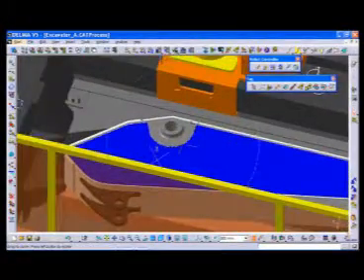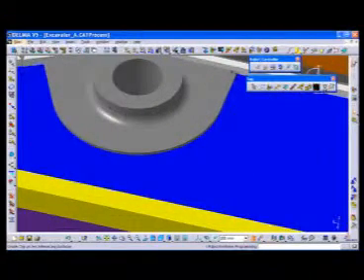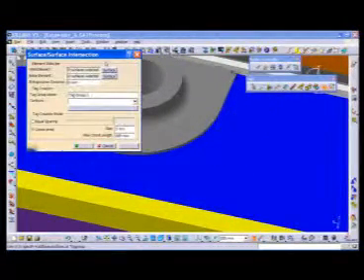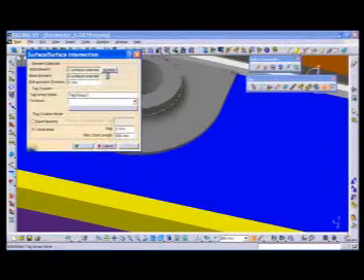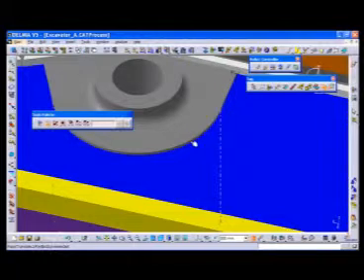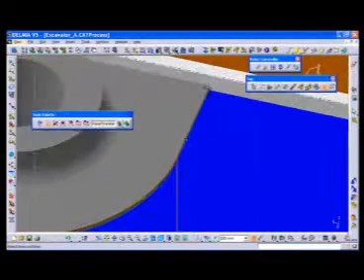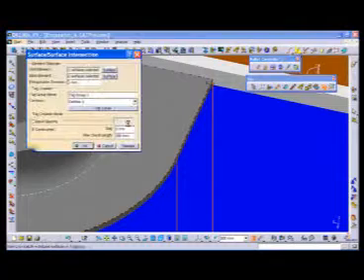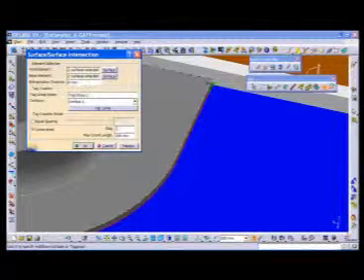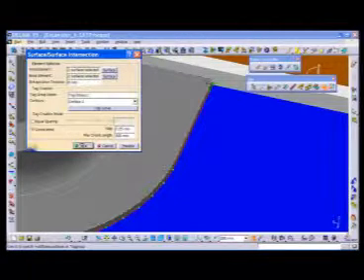Delmia calculates the angle between the surfaces and then bisects that angle. You can create a start and end point only, and this works great if you're welding in a straight line. You can create a known number of robot locations, say 12, and it will equally space them, or you can have the system identify a sag value around a curve and apply that value, so your accuracy of welding around a curve can be very high. Once we have the robot paths created, we can go into the robot teach page and apply ingress and egress locations.